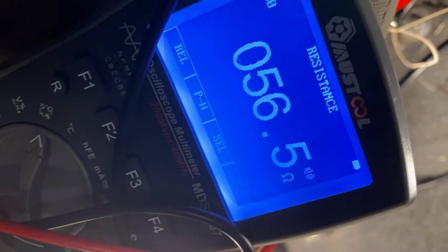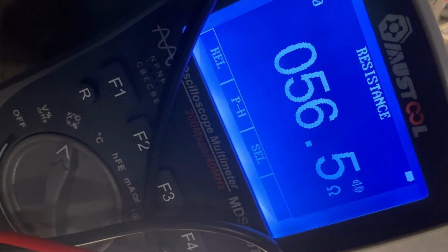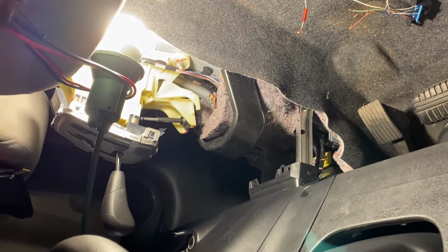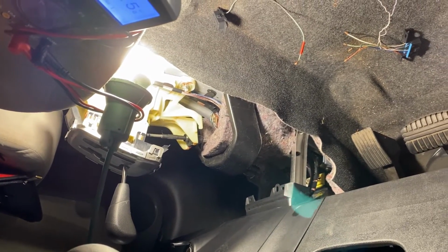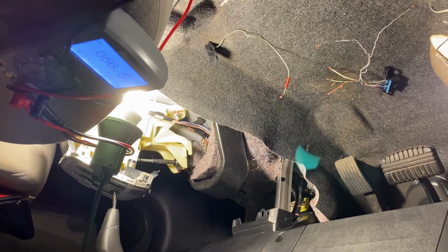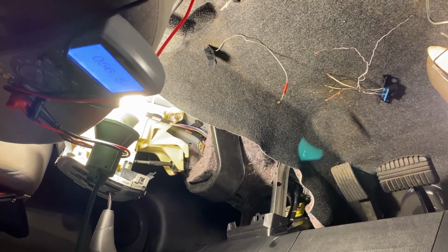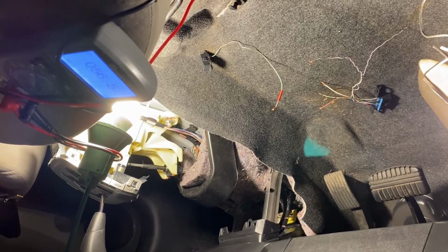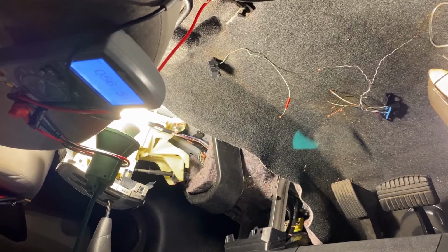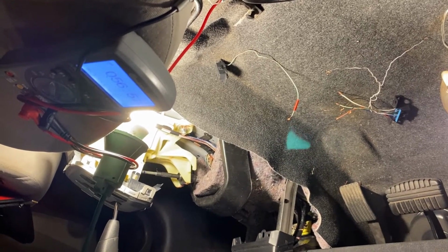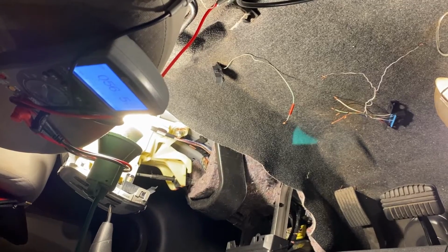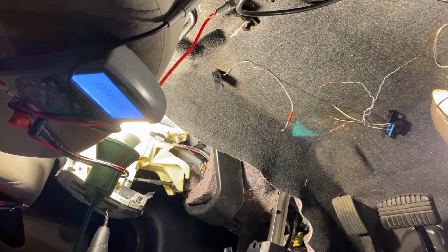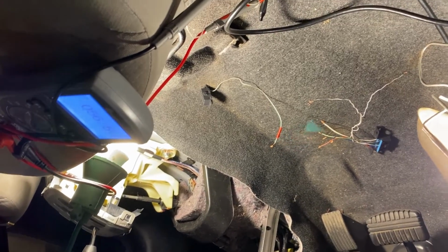ohm. So I'm not sure if I can find this part number for Mitsubishi and replace the EEPROM, or it could be something wrong with the crash data. Since I already can read the part number for the airbag module, and I have the service mode set okay, that means something is wrong. Sometimes that happens when you clear the crash, especially when the crash file is not tested. Sometimes the calculator damages the file. That's why I always keep the original file with the crash with me.